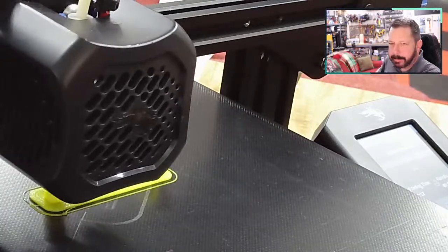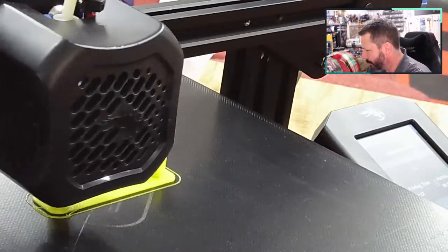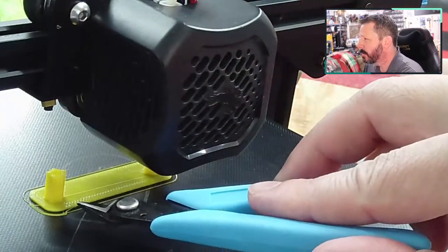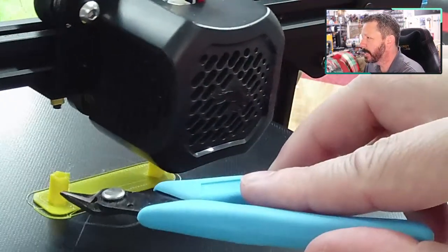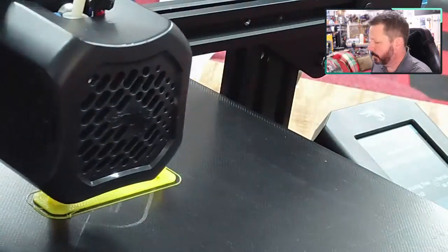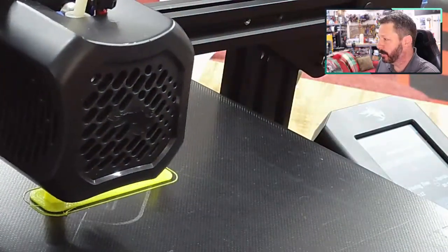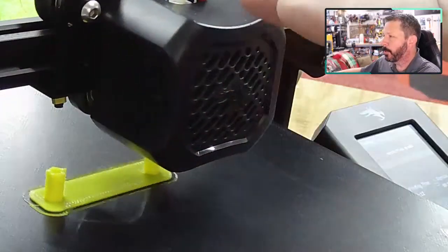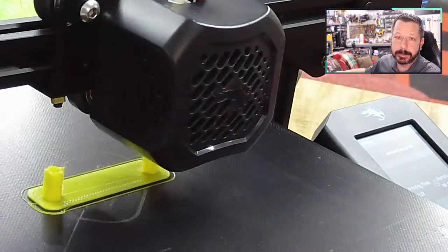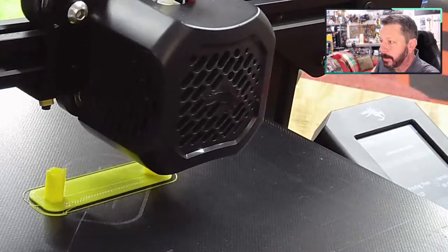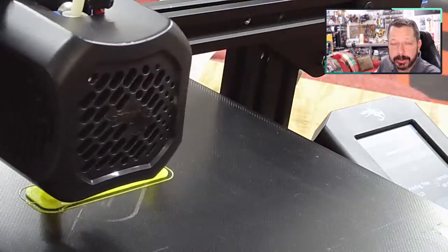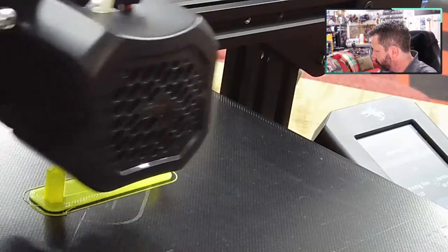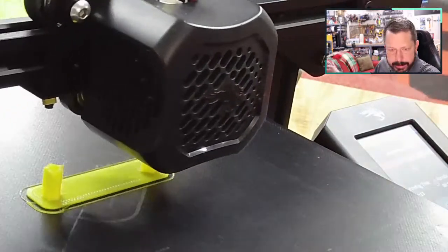It's hard to tell right now, but the first chunk with 5mm has more wisp than the second chunk, with 5.5mm of retraction, although they're still there. So I'm going to let it keep going. And if it ever gets to a point where it's clean, then I can just stop the print at that point. I don't have to finish the whole thing, because I want the least amount of retraction that I can have. Alright, so we'll let that keep going.